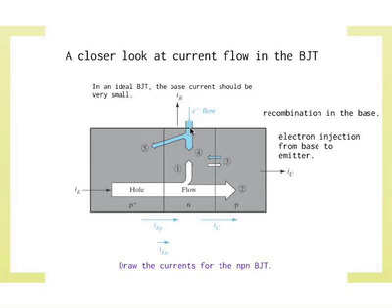Of course, because this is a forward bias junction, electrons can flow the other way as well, n-type to the p-type. So you have a little bit of an electron flow that way. You also try to minimize that. So you have these 5 components of current, which you should be at least conceptually very clear about. That's all you really need to know. Everything else is details.